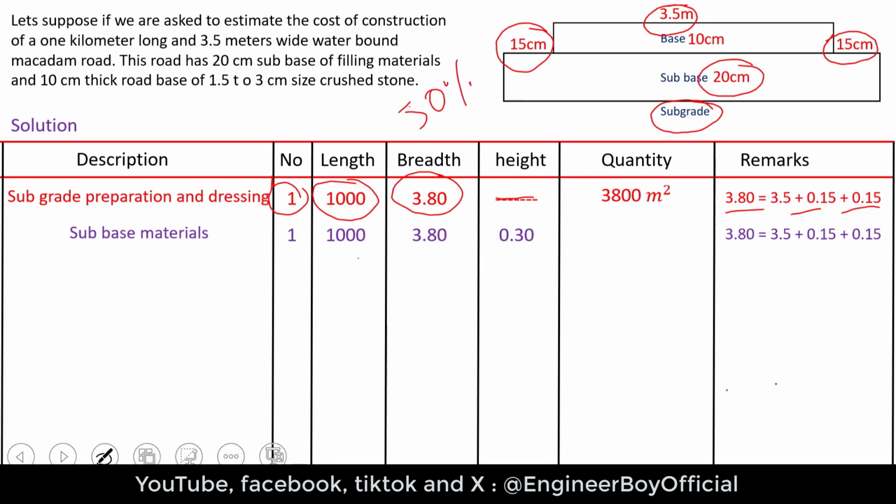I mean, if the materials are laid for 20 centimeters, after compaction they will become actually 10 centimeters, because there are voids in the materials. So when you compact it with rollers maybe, then 20 centimeters becomes 10 centimeters. That's why in advance, it's necessary to add 10 centimeters, okay?